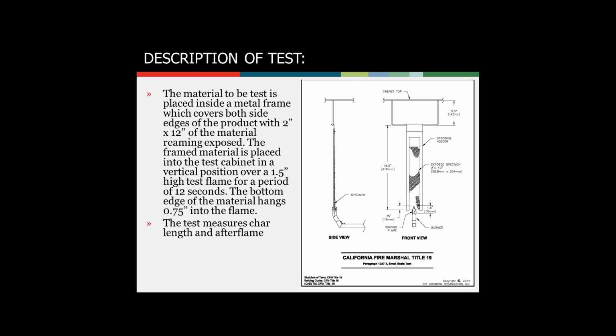In fact, this reinforces what I've been saying. When you burn a piece of treated cotton, it doesn't really break, it chars. So in the real world, other standards have changed from char length to burn length, but many of the standards still use the term char. After this conversation, I'm going to go back and make sure that California does use the word char and not burn length. But we're talking actually about the same thing. The char length or burn length is the total length of the section that is degraded by the test flame.